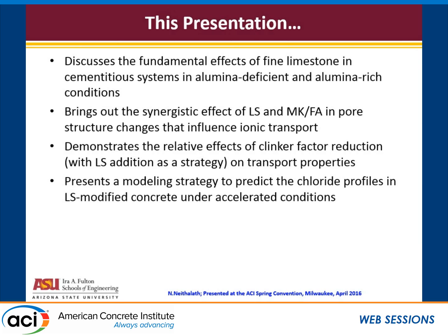The important thing that I want to bring about in this study is the idea that limestone by itself might not do all that you want to do in a concrete system, because you're loading it with a lot of carbonates. When you're intergrinding with 10 to 12% of carbonates, you have a lot of carbonates sitting in the system without doing much.